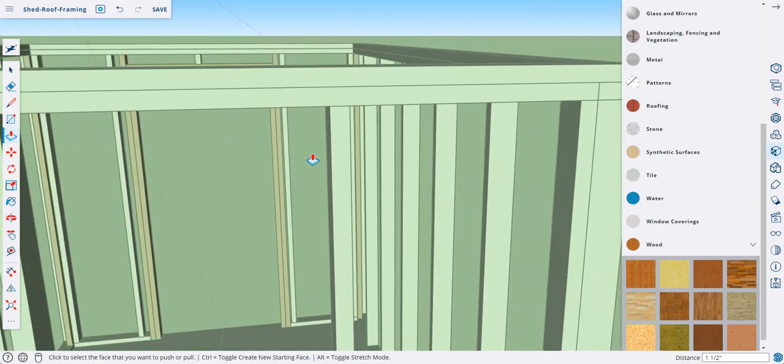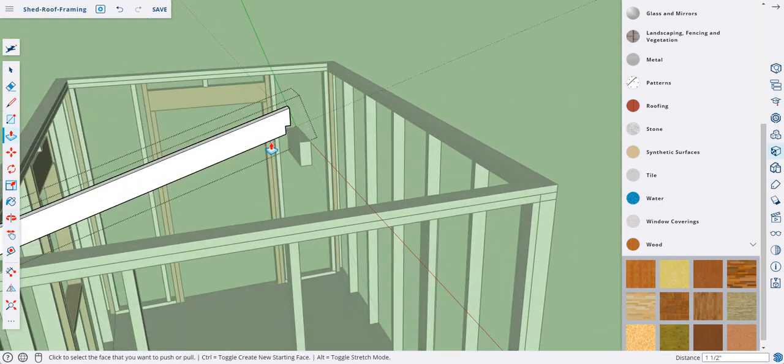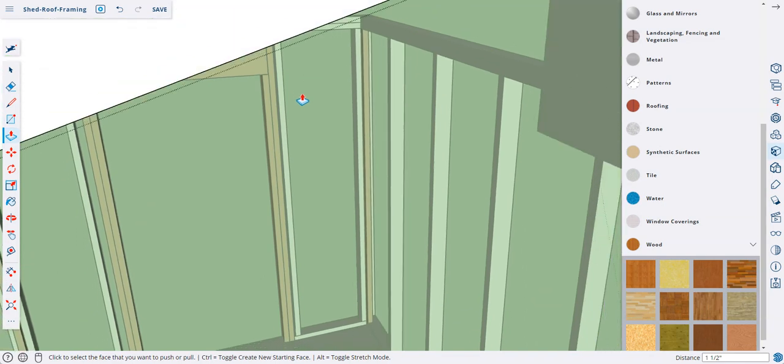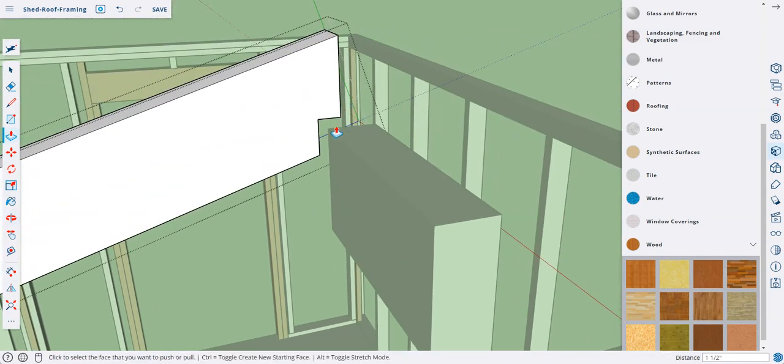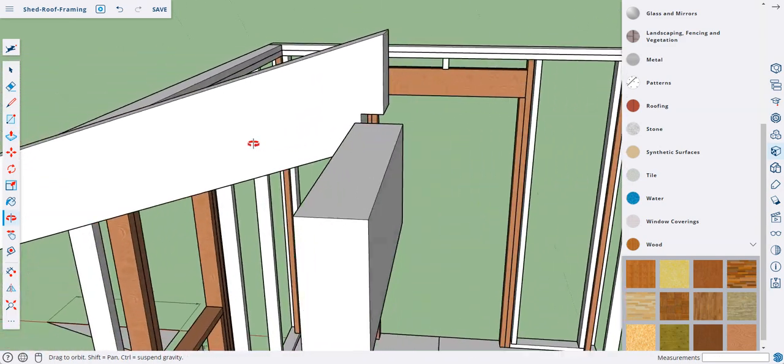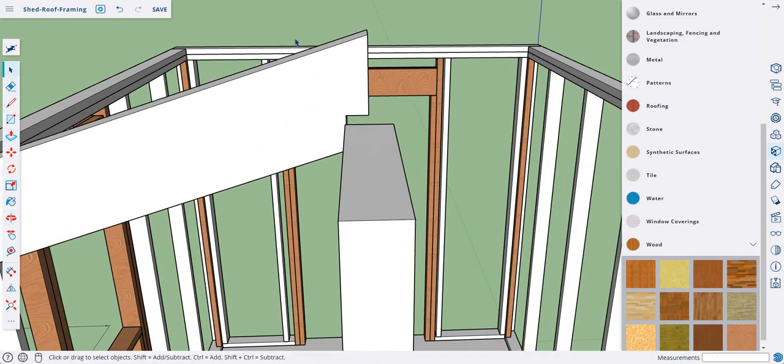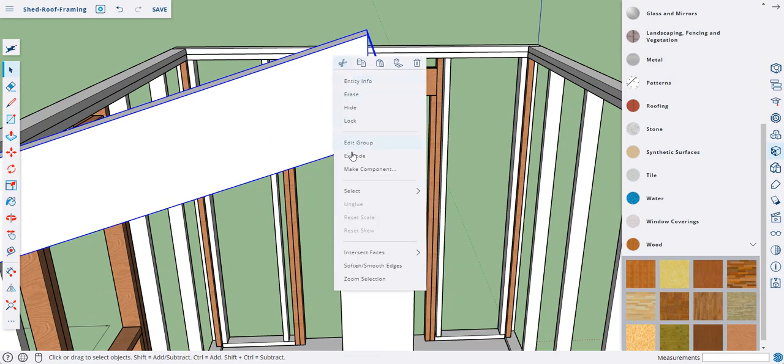And so now, oops, I lost my zoom. Okay, now we have a notch, so we're ready to close the group. Okay, and what we're going to do is we're going to select this group, right click, and then we're going to make this into a component. To make it a component means that all copies of this component will be identical.